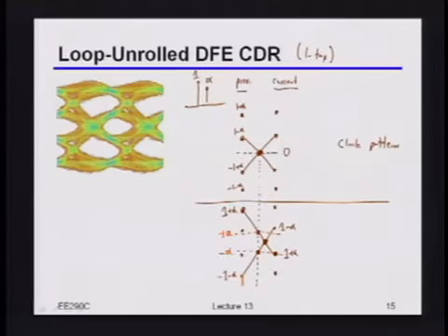Actually, maybe there are some ways you can do it. Initially you could look at the clock pattern, and then based on that, you could set the threshold, and then start again. So there may be some iterative kinds of things you could do. I have to admit, I haven't thought about it too carefully. There's probably some way you can get it to work. It's just going to involve a series of steps and estimating different things. You can probably do that reasonably well. You still, unfortunately, have the problem of this alpha for the data sampler that you can never really directly get. But for the edges, maybe you have a little bit better of a shot.